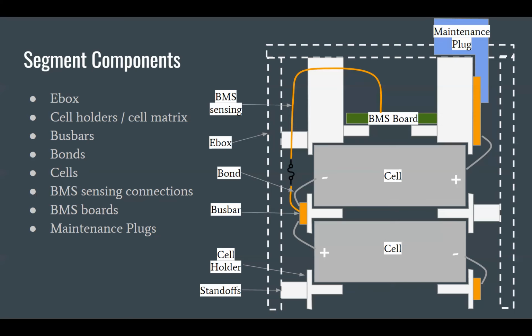And because all of the current of the entire battery pack needs to flow through that one strip of metal, we obviously need to make it quite thick. That's the downside of it. Since that needs to be super thick and then it has bonds on top of it, you then need to add elements. I do remember there was some of the reason that we also have a bolt that sticks out here, and you can spend like $12 on a singular ultra low profile bolt, or you can just make the whole thing taller and not worry about it.